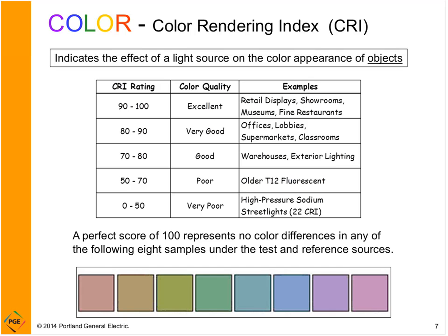Color quality scale is one that's being mentioned on that, but I think it's a ways off yet. So to give you some perspective, the sun is a perfect 100, no surprise there, has all the colors of the rainbow. Incandescent sources are usually very close to 100, and this is why retail stores still like to use halogen track lights. But we'll find out later that LED is going to be a good alternative for that.